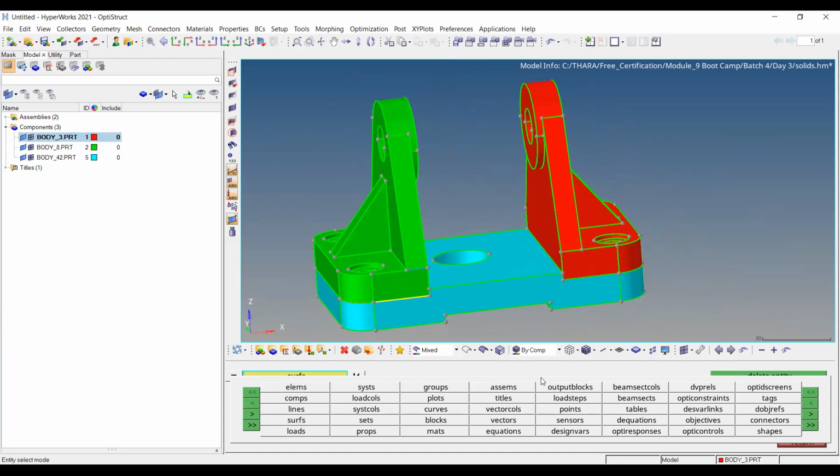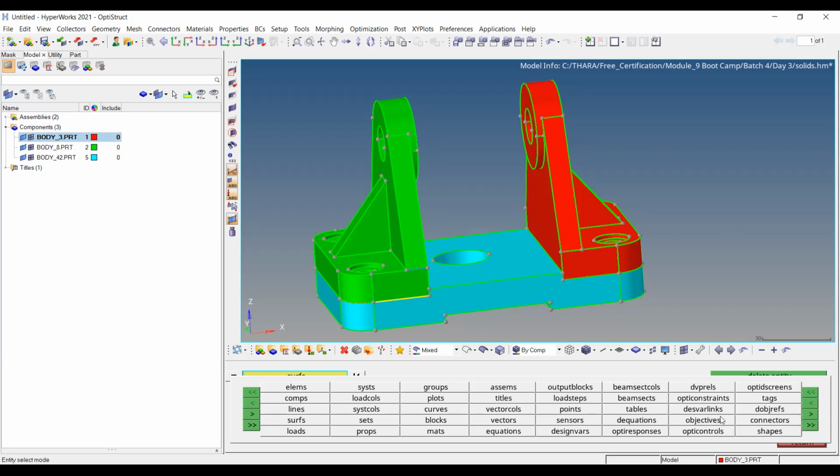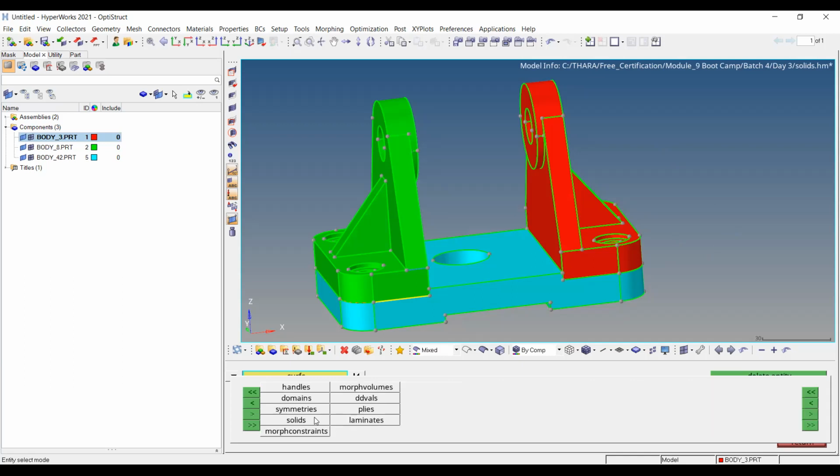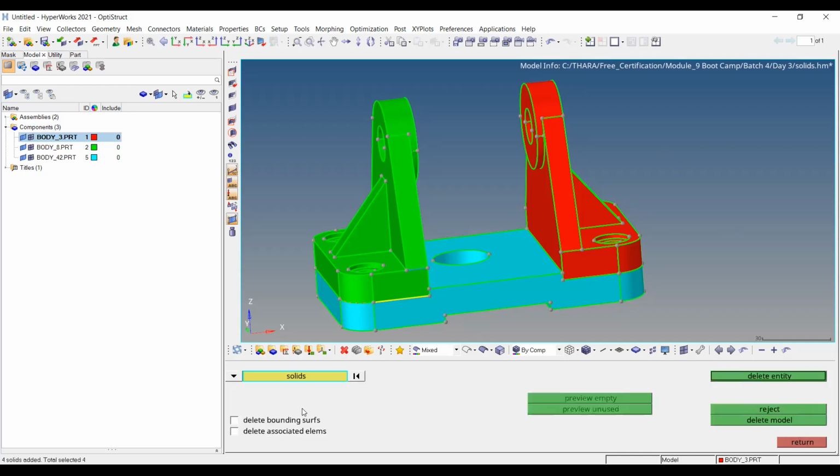After deleting the solid also, we can create the elements. If required, if it is a 2D modeling, we can extract the mid surface and create it. And we know the delete option is available in the F2 button. Click this drop down, and in the next page, solids is available. Here the solid is there.